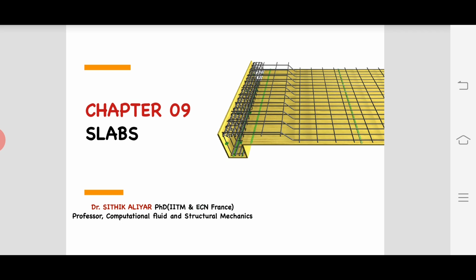So we are going to design a slab similar to a beam with a width of 1 meter, that is, per meter width of the slab. We will design per meter of slab, which is nothing but a beam of width 1 meter and very small depth. We have seen beams of depth 300, 400, 500 mm, 1 meter and so on, but for a slab the depth will be a maximum of 150 mm to 200 mm. So we'll go inside this. From the picture you are seeing, this is the reinforcement we are going to see in the slab.